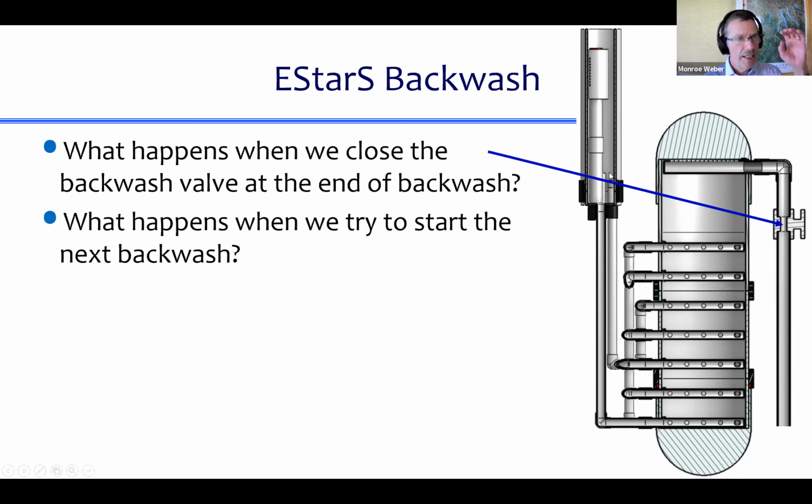which means that there's hardly any difference in potential energy available to push the water through the sand bed and fluidize it. So here's the insight. We were counting on atmospheric pressure being way down here so that there's enough of an elevation difference or potential energy difference between the inlet tank up here and where the backwash outlet is down here.